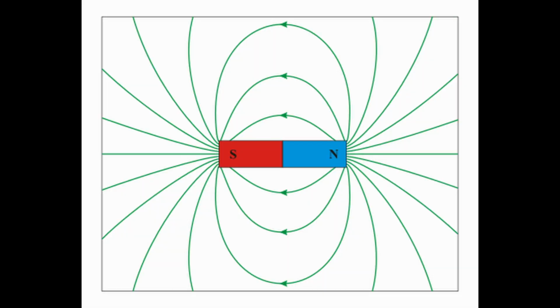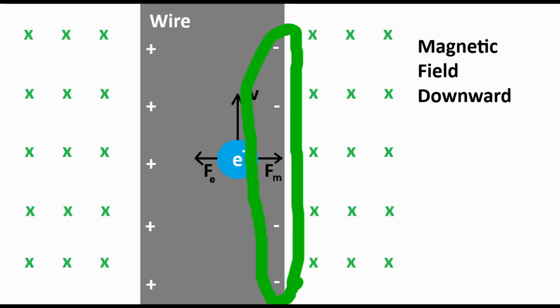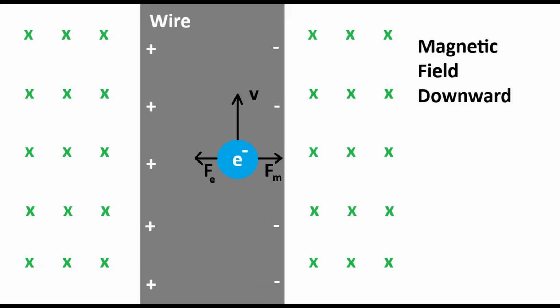We can detect magnetic fields using the Hall effect. The Hall effect occurs when moving charges, like those in a conductor, are exposed to a magnetic field. The charges will experience a force that biases them to one side of the conductor, building up an excess of charges on that side. The opposite side of the conductor is depleted of charge. The charge difference produces an electric field and a measurable voltage. If the current is constant, the voltage becomes a measure of the magnetic field strength.